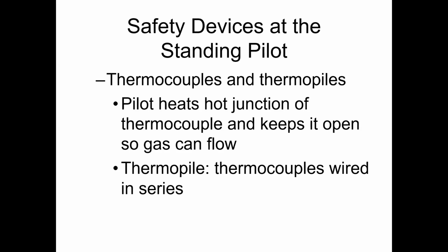So you've created electricity and you've created heat. Now, for a flame in a gas furnace, it's going to be burning, and we need to convert that flame into an electric signal in order to get our system to know that it is burning properly. This is the whole point of this, to make sure that we are burning a flame properly.